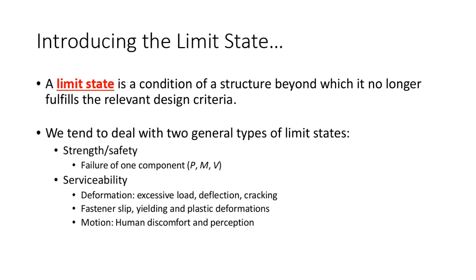Let's take my office. Let's take the floor beams that I'm standing on right now. These floor beams that are holding up this floor are holding up two different types of loads. One are dead loads, being the weight of the beam, the weight of the slab, the weight of the carpet, the mechanical, the electrical, the plumbing, all that, the permanent loads. We call those dead loads. It's also holding up live loads. Live loads are related to occupancy, what the office is being used for. So me, the office furniture, so on and so forth.